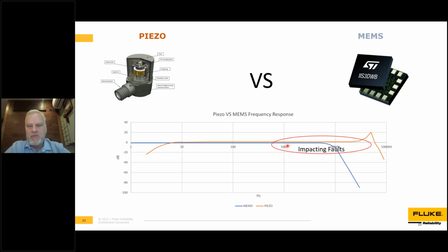And oftentimes, if you're using this kind of impact detection, that's kind of belt and suspenders with UE. And this is really where we get those early stage faults, but also with the way it's measured here, that does track into late stage faults as well. So very useful to measure impacting in these high frequency ranges. We do it natively now with our analyzers and have for the past decade. And so again, we kind of waited in the market until we got high enough resolution sensors that we could get an overlap up here.